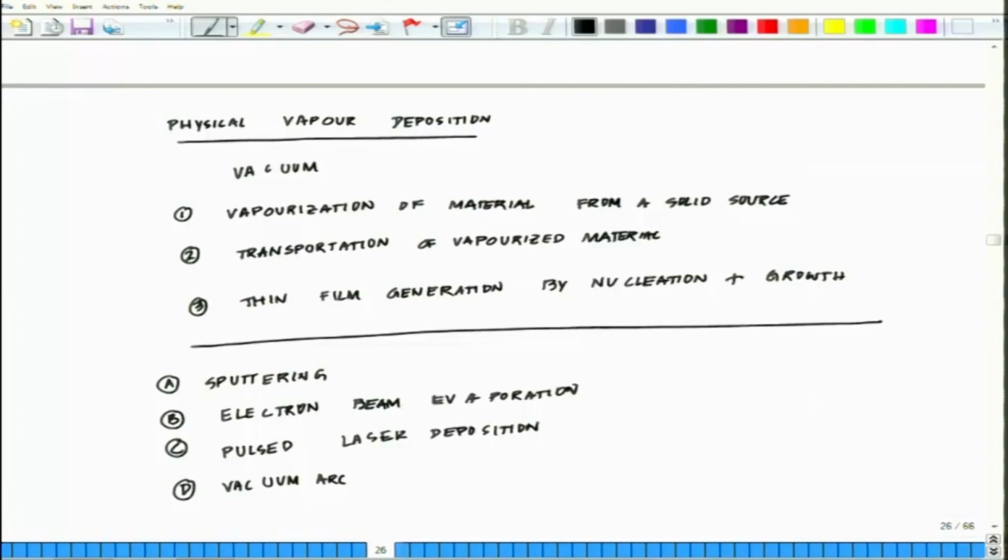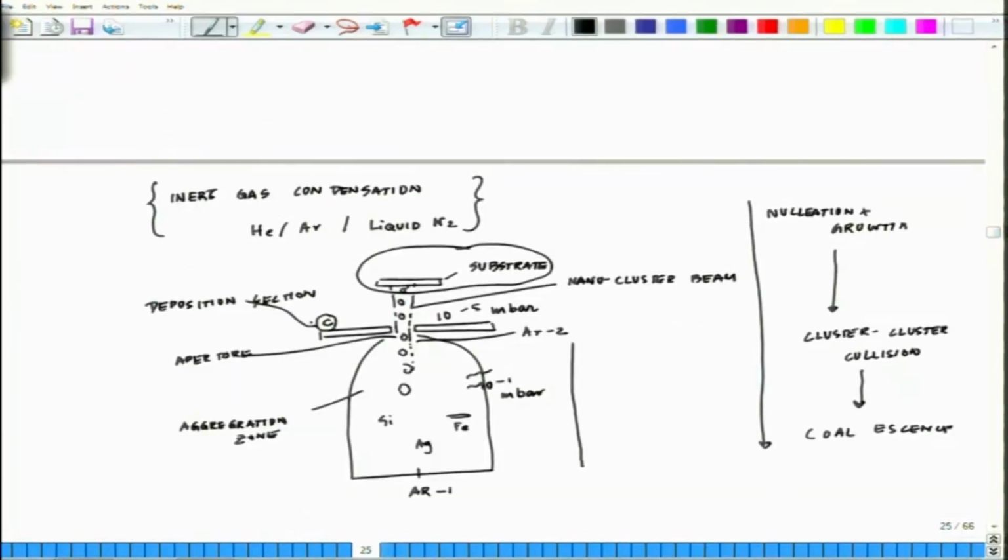So, if you follow this picture, the ejected material are then transported and deposited onto the substrate. So you are basically making them travel through this nano slit or the aperture and getting them deposited. Okay. And there are two advantages: they lead to higher deposition rate and prevent target overheating and damage. So, this is what essentially the sputtering is all about.